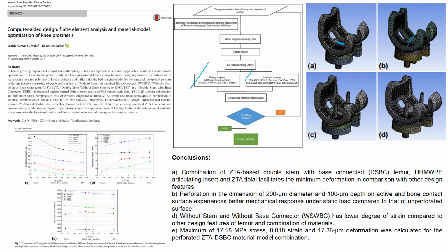This is continuous, this is gap and protruded, this is continuous and protruded. We considered 5 materials, among them ZTA, and the connected and protruded part was optimized in terms of stress, strain, deformation, all those. We carried out all the analysis through pre-process, process and post-process. More details can be found here.